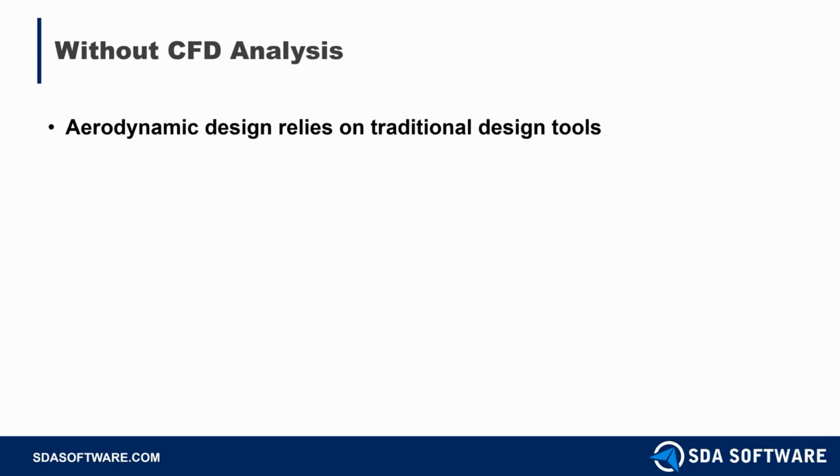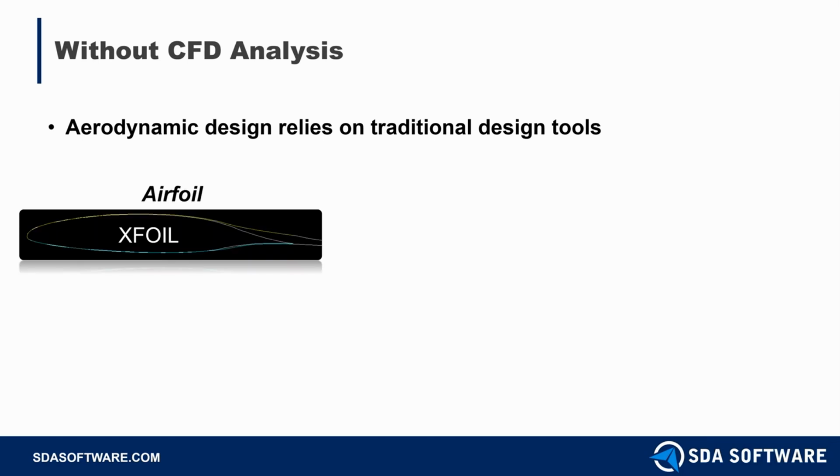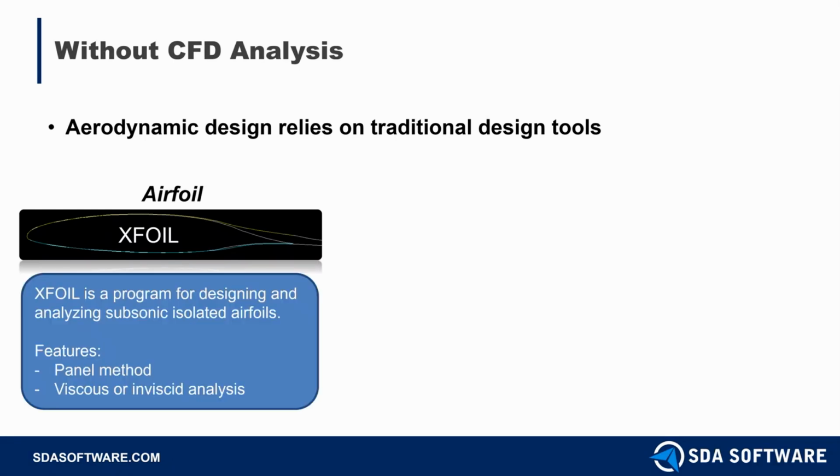So without CFD, a lot of times your aerodynamic design relies on traditional design tools like XFOIL or AVL. And typically a designer will start from two-dimensional (2D) airfoils with something like maybe XFOIL. And this program specifically designs and analyzes low subsonic airfoils using the panel method.